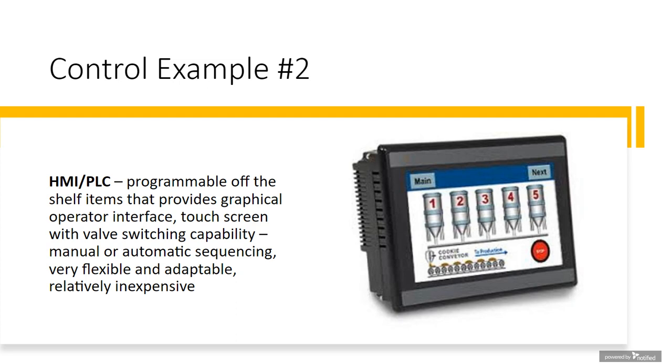The front display is a color touchscreen display, so that's the window to the operator. And that can be programmed to institute all types of recipes for doing the thermal disinfection of the system. So that's the front end of the system, the operator interface part of it. The back end is the PLC, the Programmable Logic Controller. That's the interface from the switches back through the operator interface, the HMI.